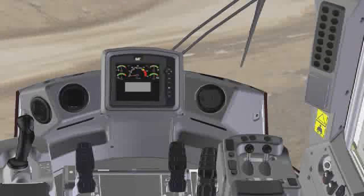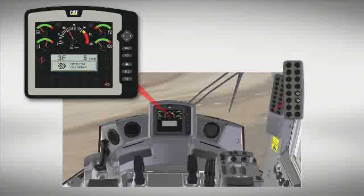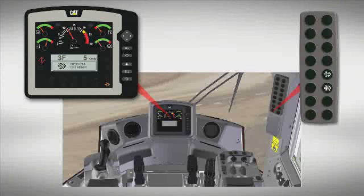The operator interface in the CAT medium wheel loader operator compartment consists of the Generation 3 instrument cluster, shown on the left. Regeneration indicator lamps are located below the gauges. Regen status can be viewed on the LCD screen. The manual regeneration and disable regeneration buttons are found on the panel located on the right-hand post.